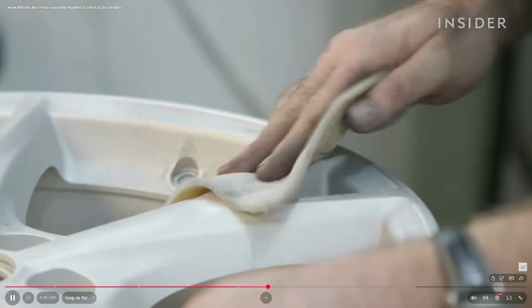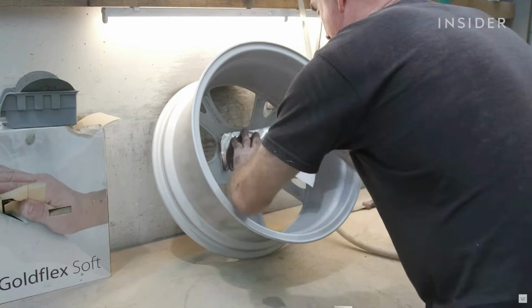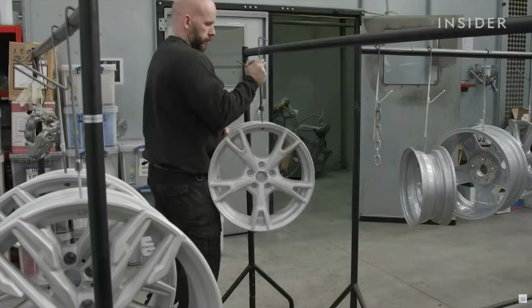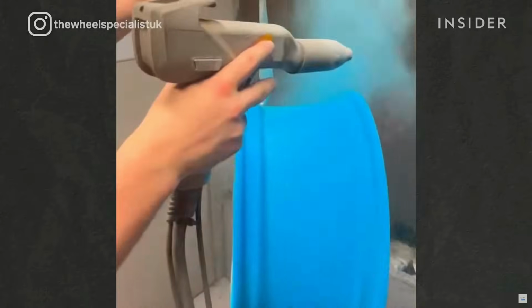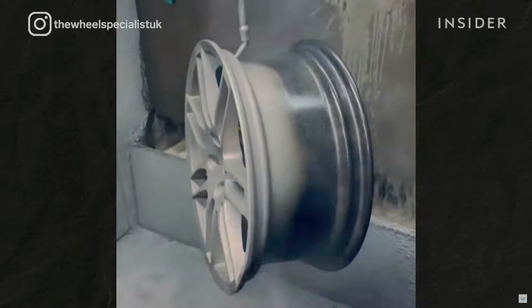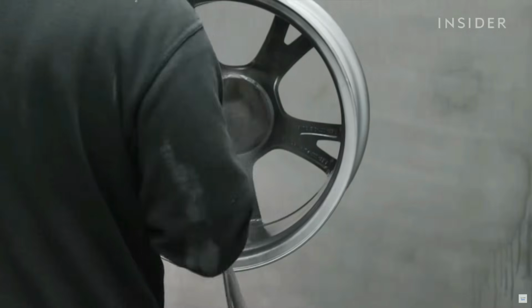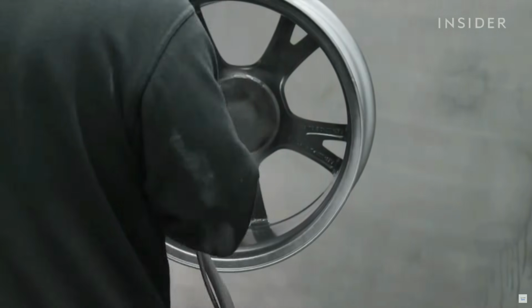Obviously, there's also some preparation. This is for a single alloy wheel. Obviously it might have been curbed. They're spraying the powder onto the workpiece, as you see there. It'll be evenly coated. Now that back wall, as you see there, has got water running down it. Any overspray will be sucked into that wall, so you're not breathing those in.